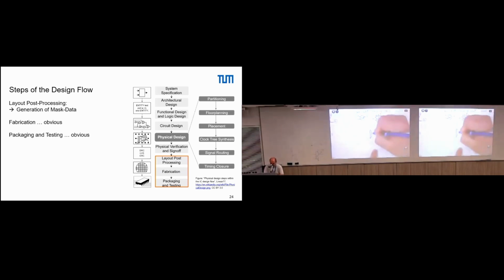In our case, I just use 2 because I don't want to draw too much. The output here is effectively C. We have fixed 0 and 1 here, fixed 0 and 1 here. We have fixed value routings here. The one selects this one, the other one selects these two, which we can then connect to A and B.